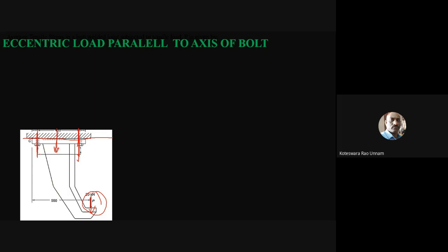So first we need to identify the effect of this load by transferring it from this plane to the plane which passes through the centroid of this bolt system.